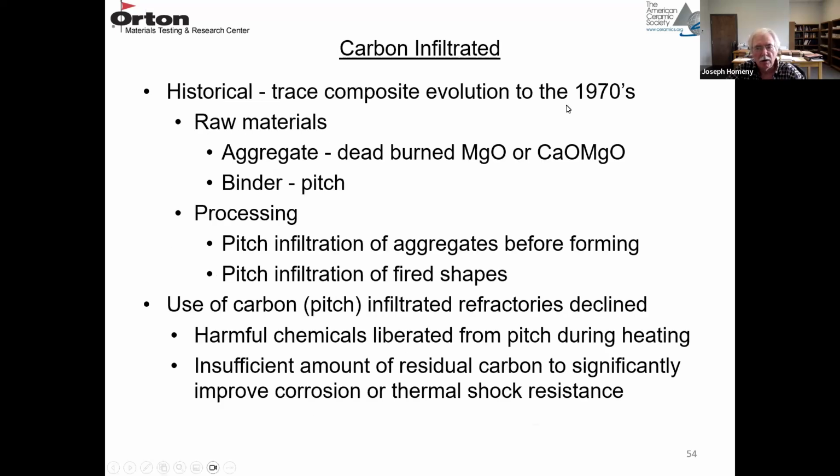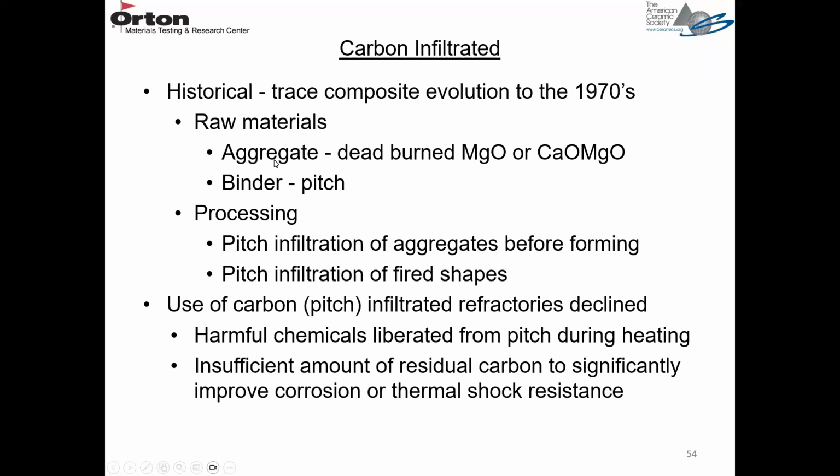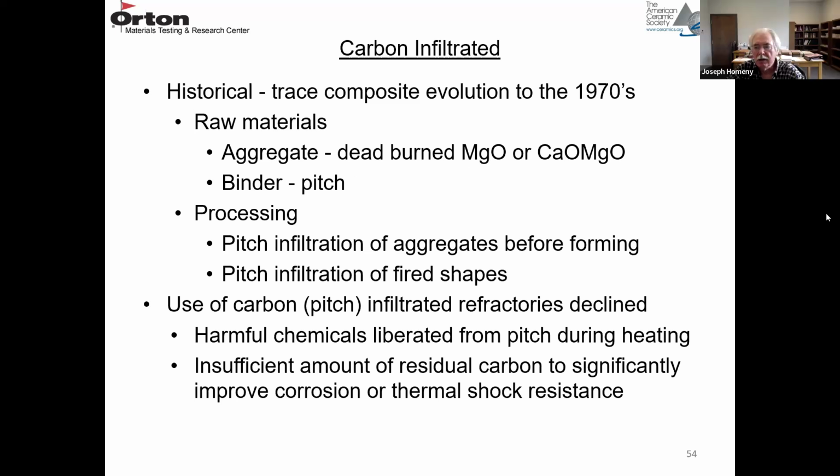So the composites really started in the 1970s, and the raw materials, the aggregates, dead burned MgO and dolomite, and the binder was simply pitch. So there were two ways of processing these, pitch infiltration of the aggregates before forming, and then pitch infiltration of a fired refractory shape. And these were made with pitch.